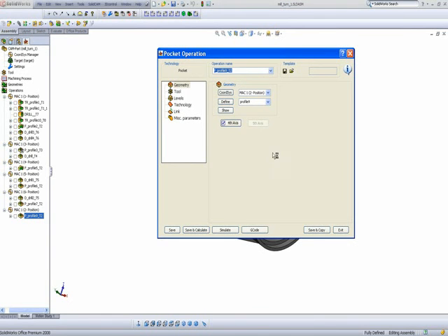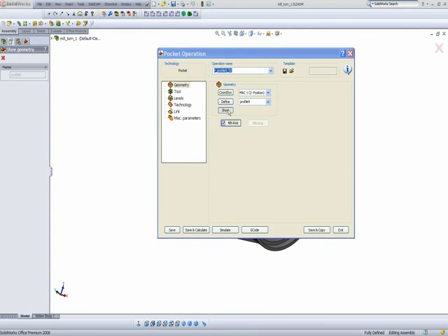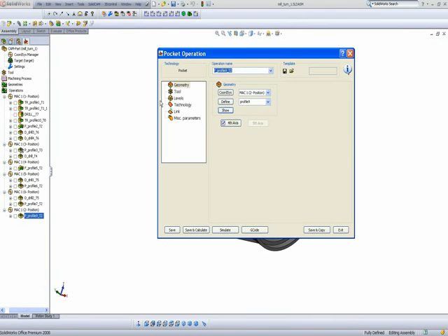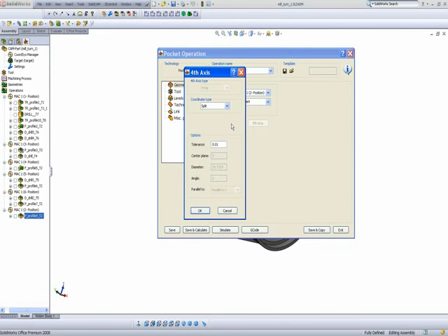If I were to look at the operation itself, you can see my geometry is on the floor of the pocket itself. And you'll note obviously that the floor is not a straight floor, but it's actually wrapped around my x-axis. So we have now the option over here on the bottom called 4th axis. If I were to open it up, you see we're working on a wrap. Like I said, we wrapped around, and we're wrapped around the x-axis.